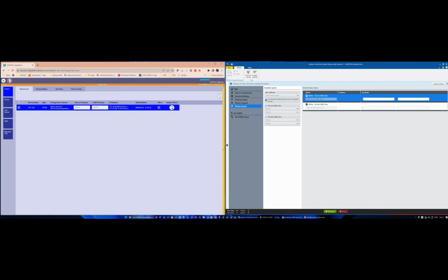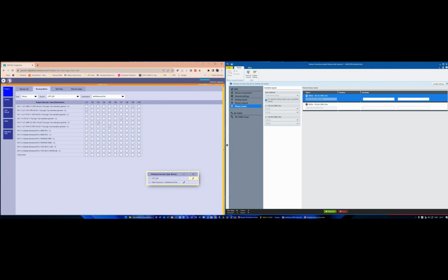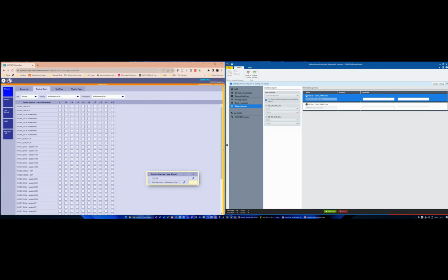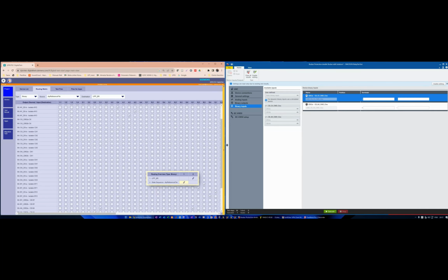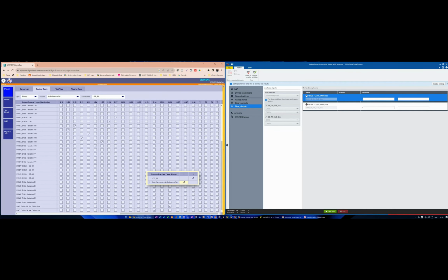And here in SIPROTEC Digital Twin, I route my IP reference to my relay protection, my bus bar protection, and I put these two signals. What I have done is, if I give the close command to my bay CX, we can see that I linked it to this binary input of my bus bar protection, which is a binary input of the close command.